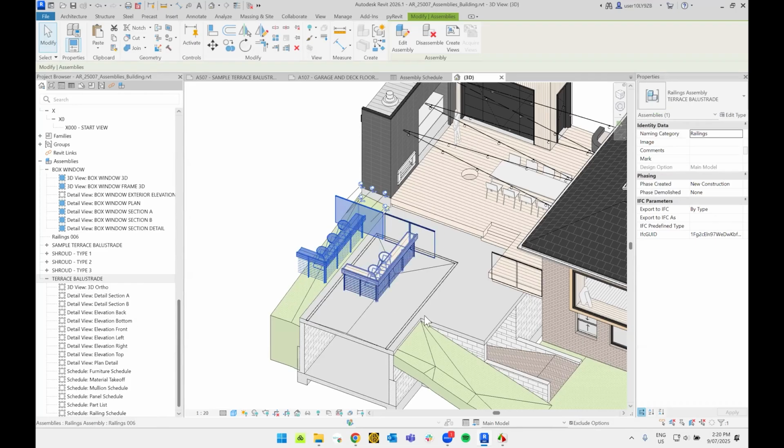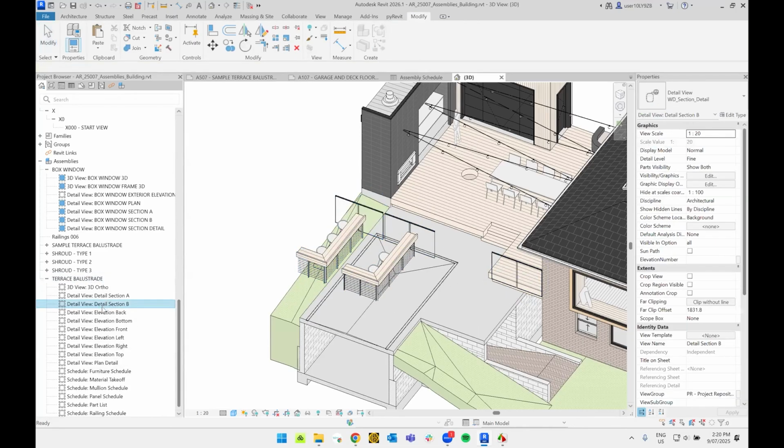However, doing so, we've actually moved the assembly, right? That will upset our sheet, and it will mean that the views will all be offset. So it's not as good as, say, having a project repository where you keep these elements often in their own space.